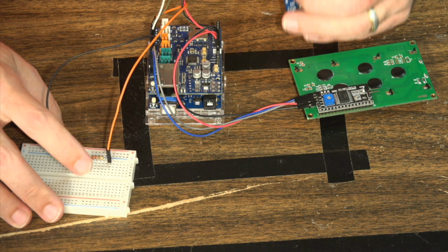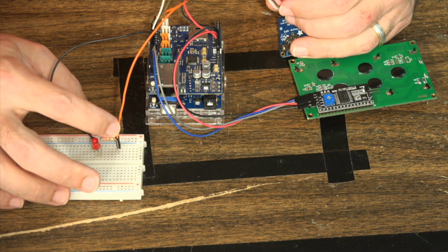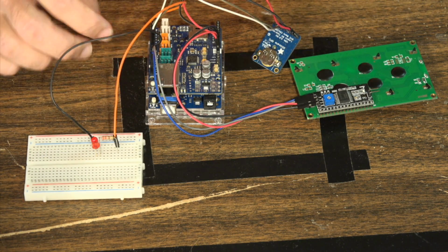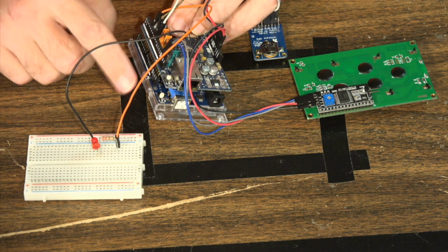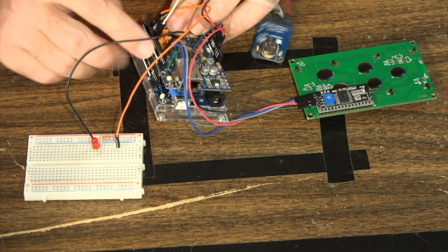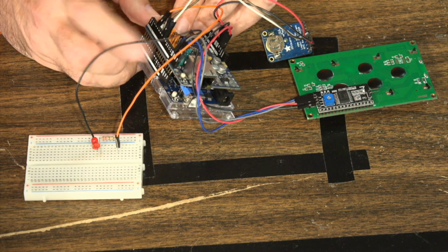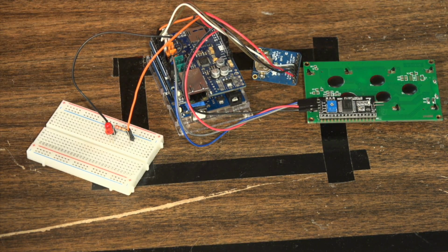Beyond that, we do have our little red LED here, standard red LED. We have our standard resistor. This is going to be connected to digital pin 3. So basically when digital pin 3 is turned on, that will then turn the red LED on. And for the ground, we're simply connecting the ground over to the ground on this side of the shield. So this is basically what this particular project looks like. And, you know, as projects go, it's a rather simple wiring job.